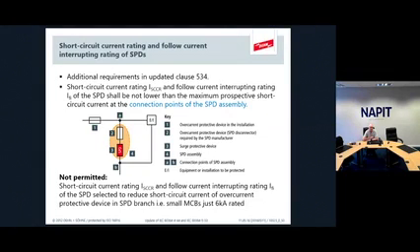So one of the other things we need to look at is the SPDA, or Surge Protection Device Assembly. Now in this diagram, what we're interested in is the performance of the fuse, the cables and the SPD. This is most important for the Type 1 device because in the regs it says the value of the SPD is 12,500 amps. That's what it's got to deal with in terms of lightning current. So you can't feed a Type 1 device with a 6 kA MCB. What that means is that during the surge event, the 6 kA breaker will break, you disconnect the SPD, and then the rest of that surge current goes straight into the installation.